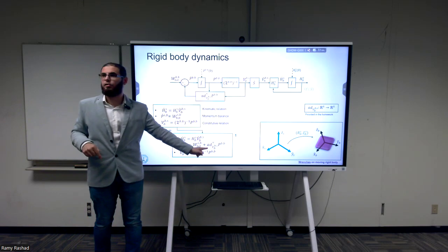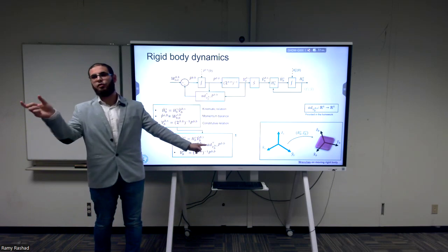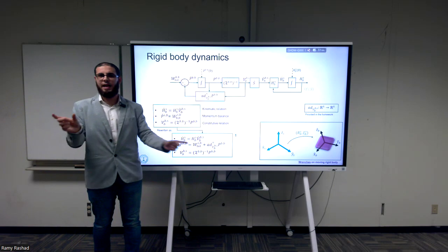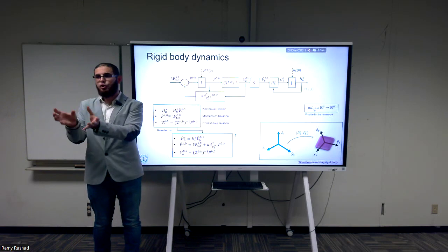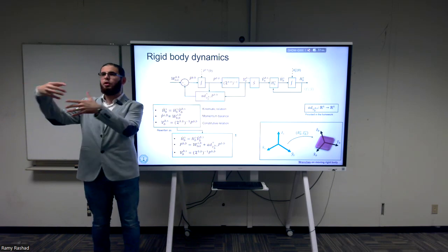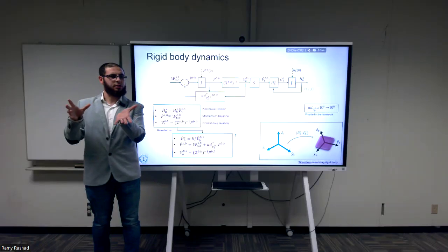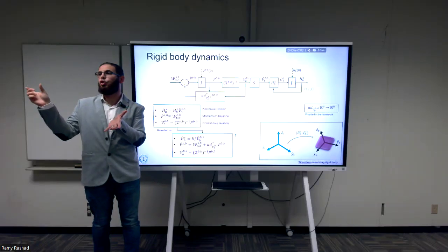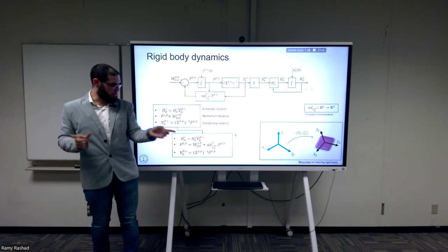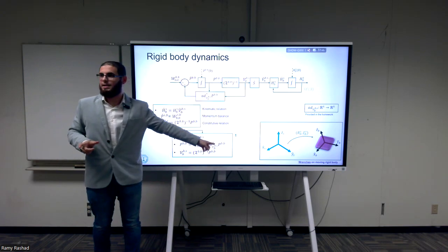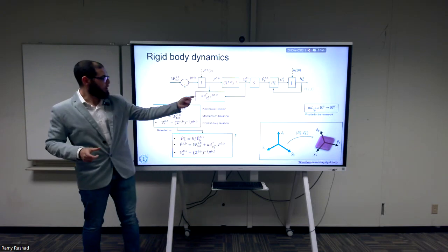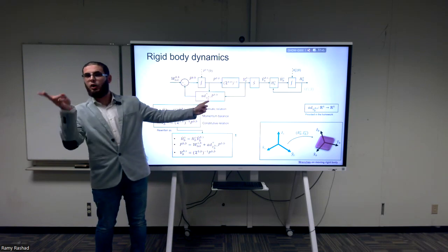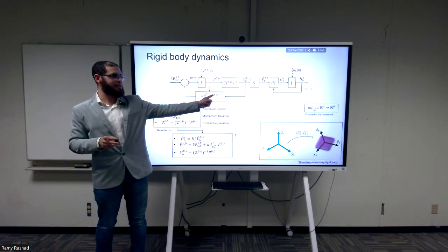And we get here an extra term. This is precisely the same as the extra term we got for the gyroscopic effects, but now you can consider it will be the gyroscopic effects plus some extra term that will couple rotation and translation. This extra term is precisely what you know as the Coriolis forces. So Coriolis forces will come in this term here. This term here, again, I just write it like this. It's also a nonlinear function. It's a coupling between the twist and the momentum.